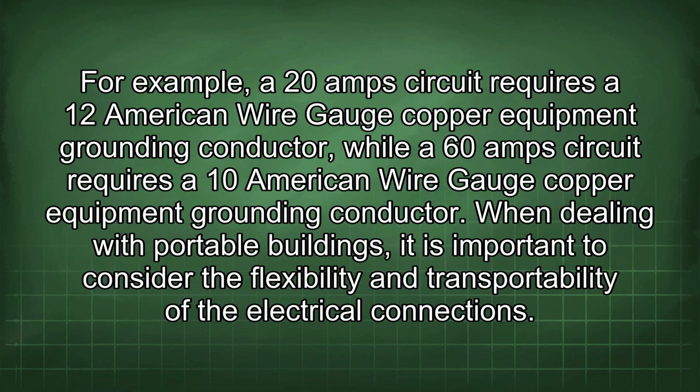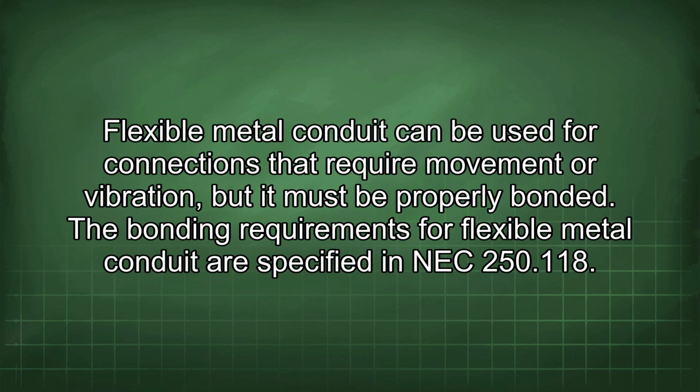When dealing with portable buildings, it is important to consider the flexibility and transportability of the electrical connections. Flexible metal conduit can be used for connections that require movement or vibration, but it must be properly bonded.